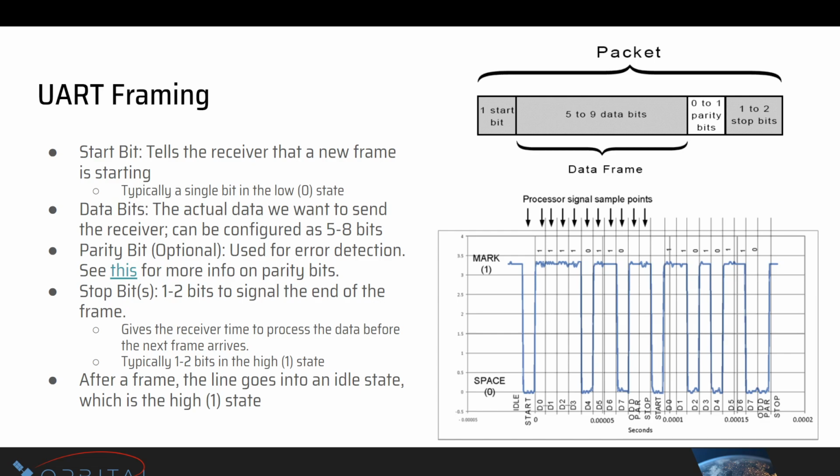Yeah, but that would give a lot of work to the MCU, and you want the MCU to do other work rather than always data processing. So usually you offload it to this single circuit or chip. And that circuit would be basically pure hardware, usually, like an ASIC.